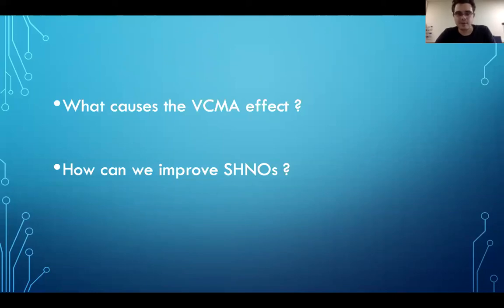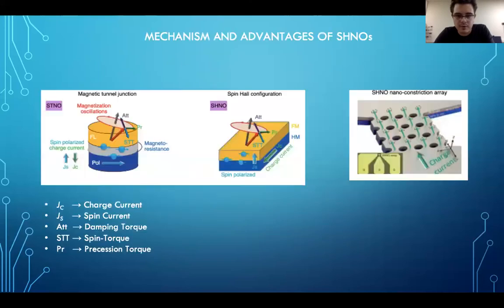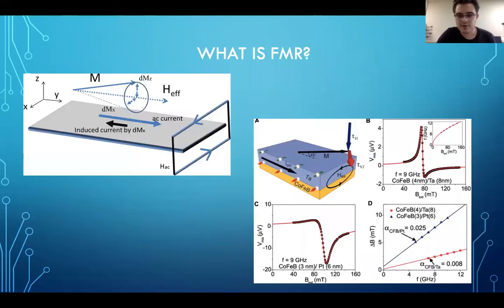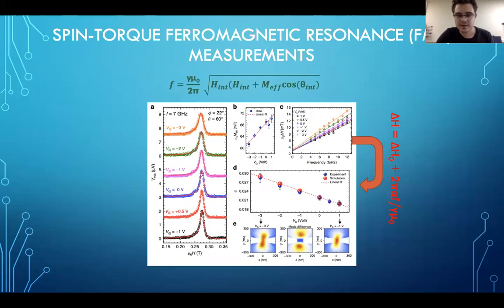And the second effect is bigger. As you can see, we put magnesium oxide at the top of the CoFeB layer. And if we apply a big voltage difference, and 4 volts is really big for our tiny device, whose diameter is 150 nanometers, oxygen from this magnesium oxide layer may migrate into the CoFeB layer and the ionic bonds with this CoFeB layer stop. This creates a much higher effect at the threshold current.